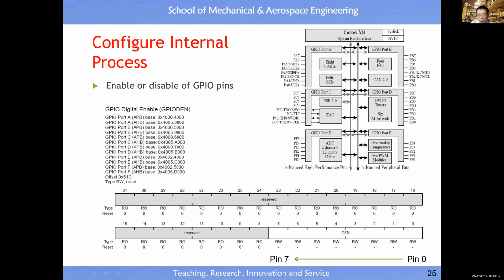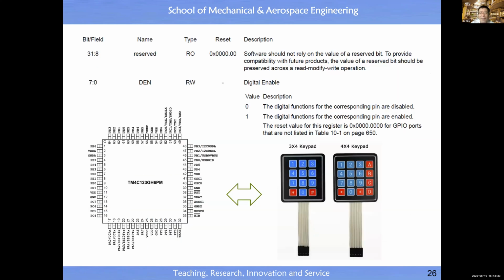So you have 6 ports. Each port gives you 2 address buses to open the port in order to configure it, right? So you have 2 address buses, all right? Then each port has pins. For each pin you may tell whether it's input, output, etc. Okay, so like it. And why do we still need to have an input?